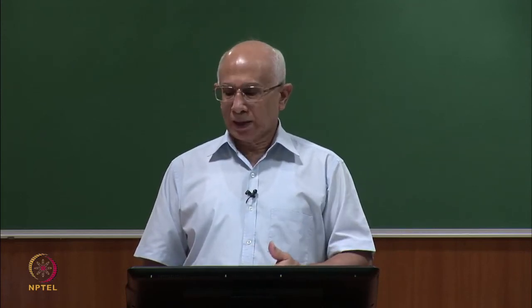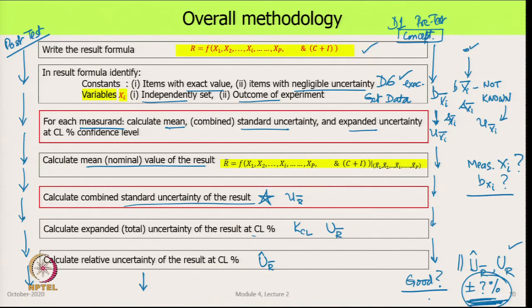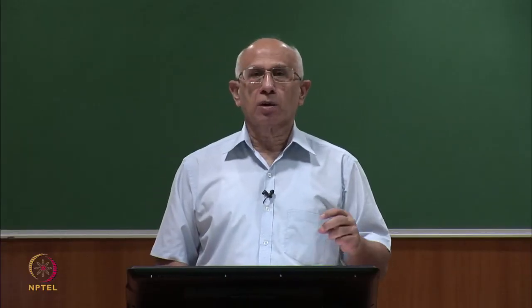We do that check calculation and then compare it with what is needed, and we can say to them that yes, my uncertainty is less than yours, we could do it, or that my uncertainty is more than the value that you want, my setup is not good enough for your purpose, I cannot do the experiment. So, that is an example of the use of uncertainty analysis, where even before taking any data, we can decide whether an experiment is doable or not doable.